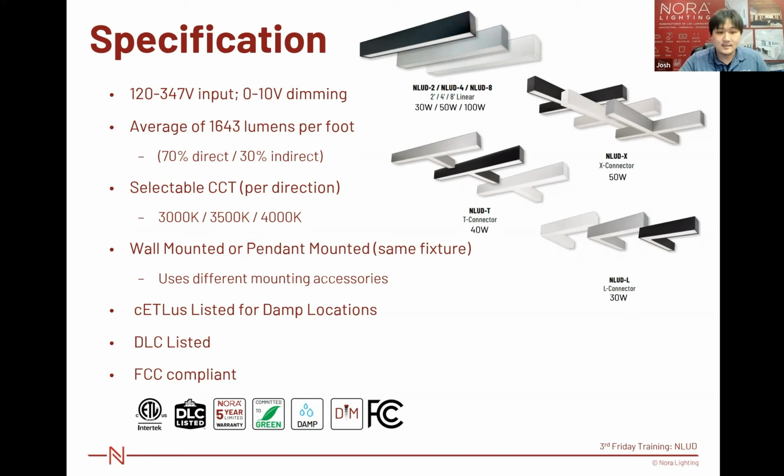It has a selectable CCT switch on the top. You can switch it to different CCT, both up and down, and it's per direction, meaning you can change uplight to 4000K and still keep the 3000K downlight. And it has one more switch, and you can choose to either do only downlight or only uplight.